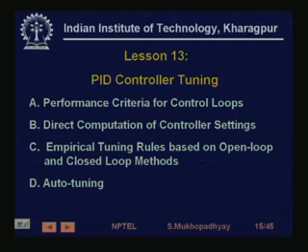These gains have to be properly set so that you have good response, because the response of the control loop is directly related to a number of quantities, mainly product quality, energy efficiency, raw materials that you are consuming and things like that. So, it is very important to have control loops well tuned, so that efficiency of production can be achieved. We looked at various methods of tuning, starting from analytical computation based on models, then empirical tuning, which is based on experimental results,